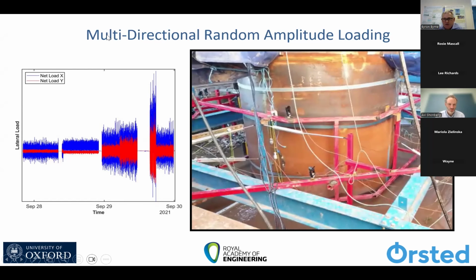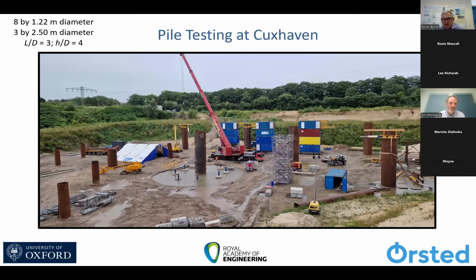And then we repeated it all at Cuxhaven. So what I've shown so far is the testing at Cowden. We did it all again at Cuxhaven last year. The testing took about 12 months from start of installation to completion of the testing. This was at a quarry site. We had to excavate down to the water table so that we're testing in fully saturated material.